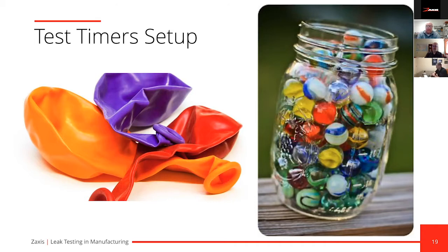So if you have a softer part, or parts maybe with seals, or a balloon, or maybe it's a bag or something else, that volume change while the test is occurring is going to show up later in the test step when we actually start watching for very small changes in pressure. Because we have such great resolution, either a change in volume or a change in temperature shows up on the screen of the tester as a change in pressure.